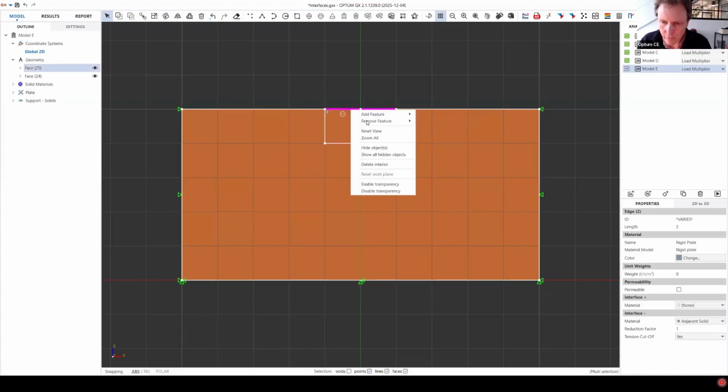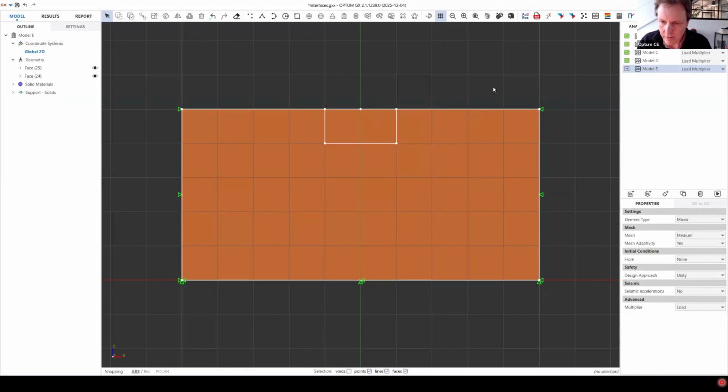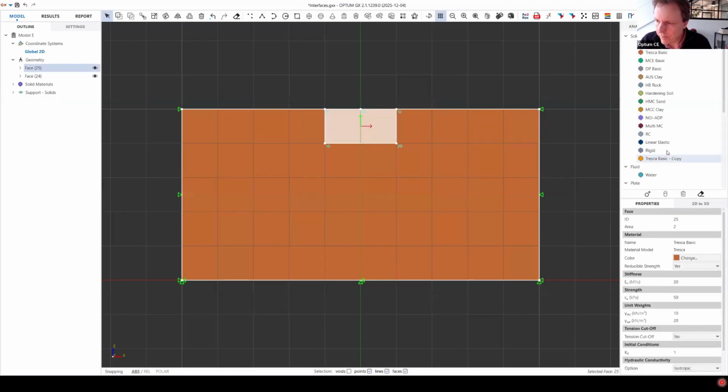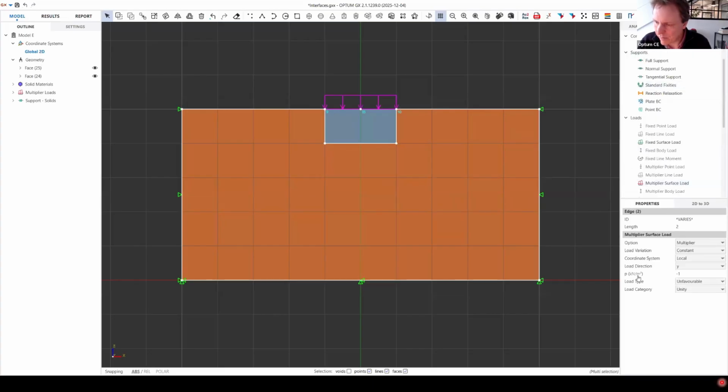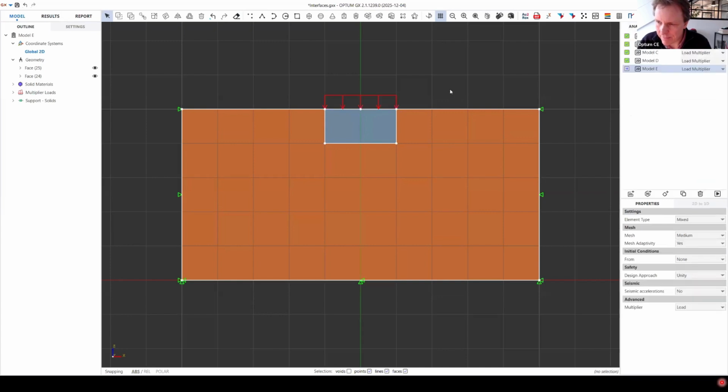just delete all of this. So this is one version of it, and I have a rigid solid. So to solids, only surface loads apply, so kilonewton per meter squared. Because if we start applying not point loads, but concentrated loads, line loads like this, then we have a stress singularity, and we eventually get to a limit load of 0. That's how it is.